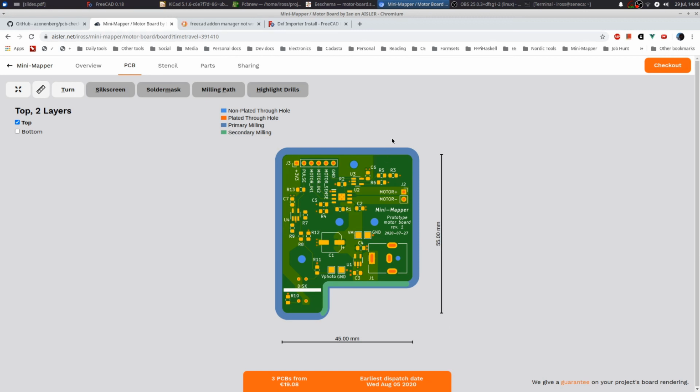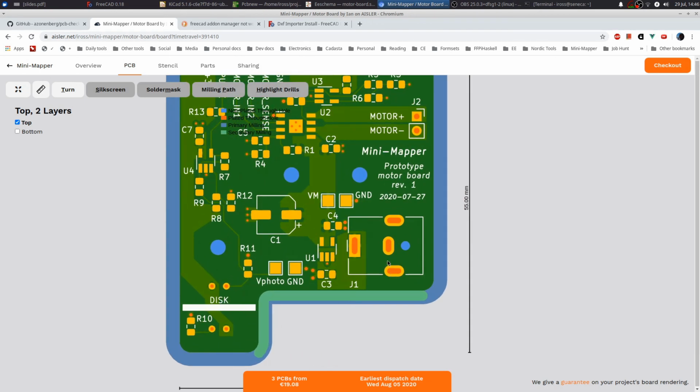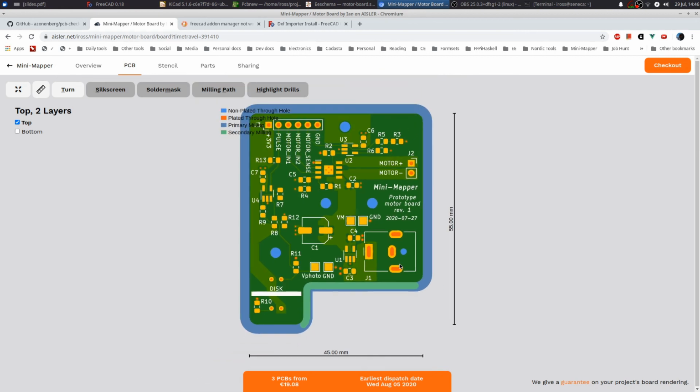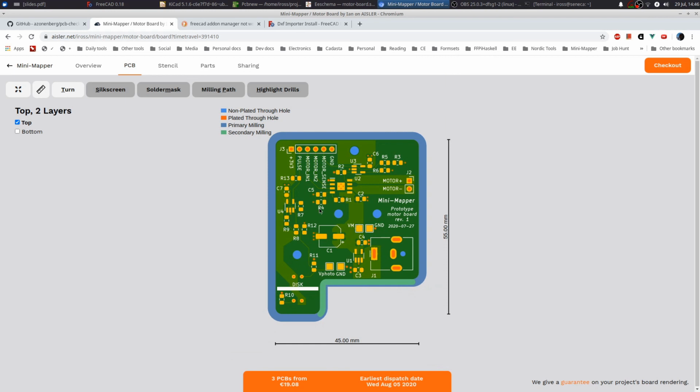And they also have a thing where you can order with simple and slack design rules very quickly, or you can wait a few more days and you get nicer design rules. And if you end up having things that have plated slots like this, you need to use their higher quality service. But I think it's only 5 working days, so it's not really a bother. So they really are kind of the Oshpark of Europe, I think.